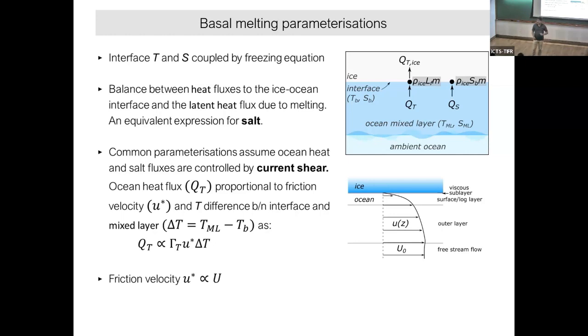Even in an experiment it is difficult to measure the flow next to the bottom surface. Only DNS can capture it. Even the large-scale model cannot, because nobody knows exactly what happens at the next grid point, where the velocity changes exponentially or parabolically or whatever, right? Unless you know these points, you cannot fit the line, and from that line you calculate a gradient, and from that gradient you calculate U star.